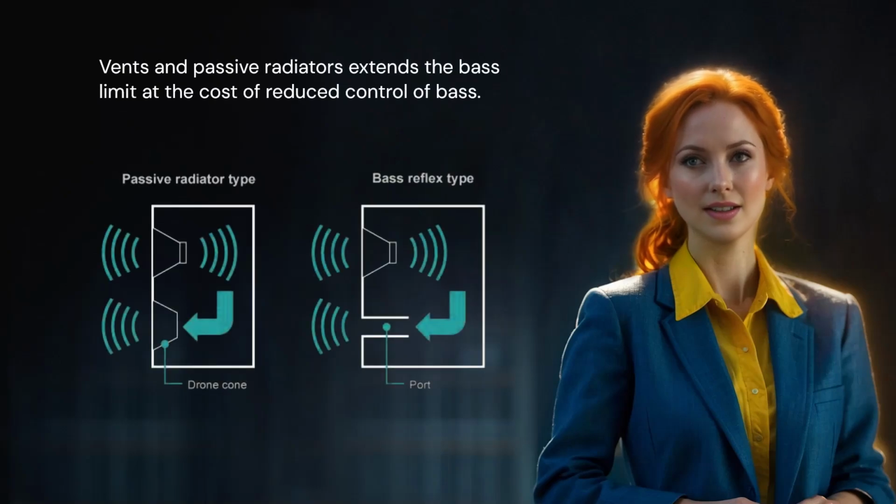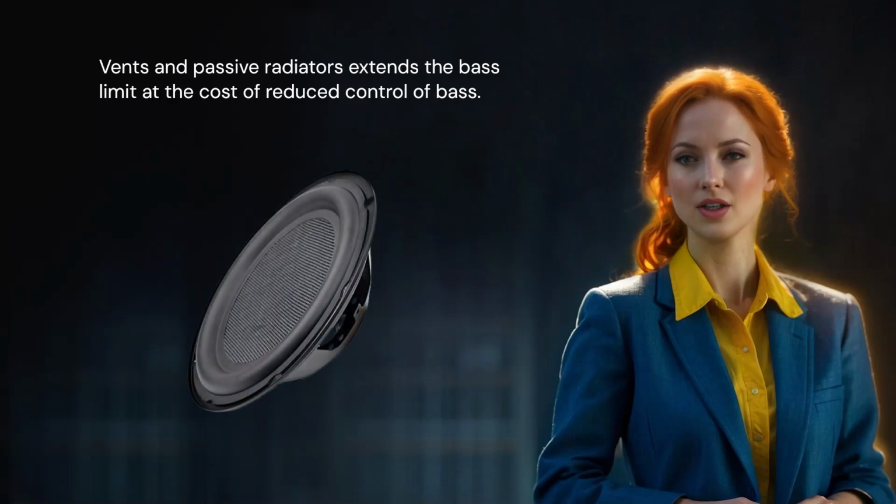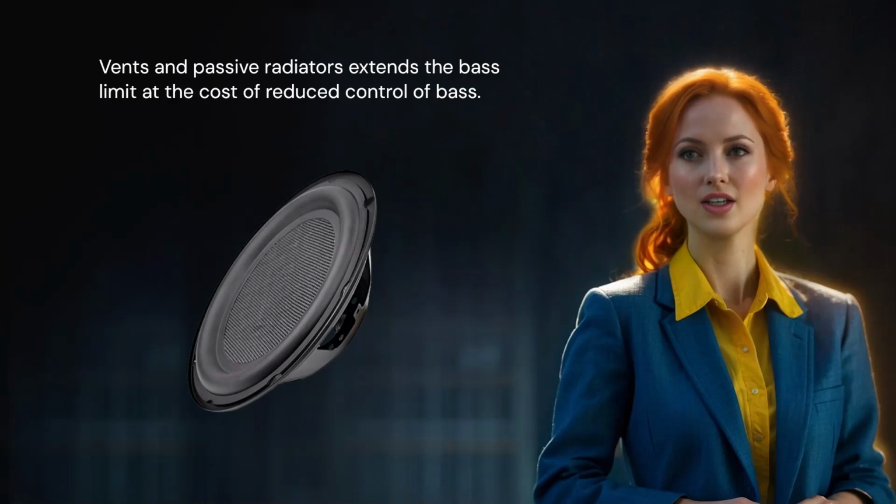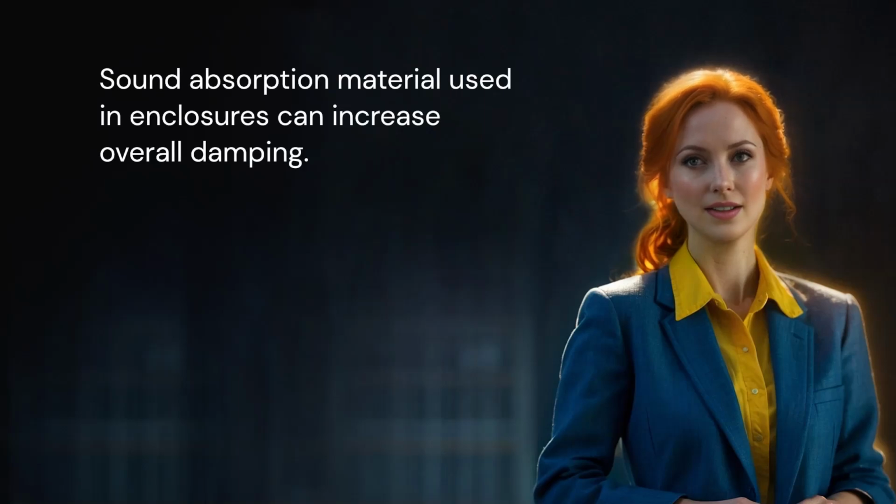By incorporating a ventilation port of proper diameter and length, the speaker's bass extension can be enhanced, allowing it to reproduce deeper bass notes. Alternatively, ventilation ports may be replaced by passive radiators, which resemble the low-frequency driver of the speaker, or the woofer, but lack a voice coil. These radiators serve as dummy masses tuned to lower natural frequencies than the woofer itself, thereby extending the speaker's bass range. Also, the use of sound absorption materials within the enclosure helps control air oscillation, and hence increases overall damping of the system.